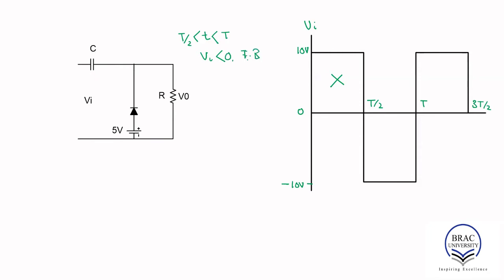forward biased. Now, let's consider the diode is not an ideal diode, the diode is a silicon diode. That means we're going to consider the constant voltage drop model. When the diode is on, we're going to replace the diode with 0.7 volt. And one thing you should know, we're going to analyze the clamper network for two half cycles.